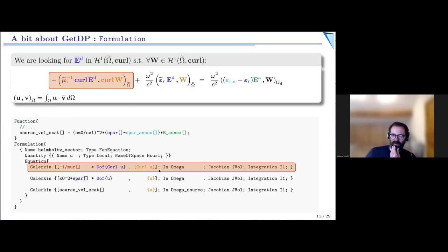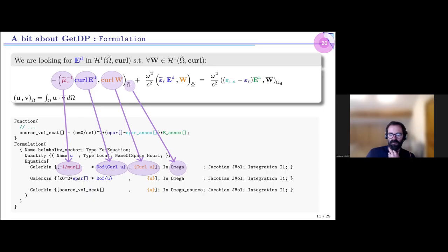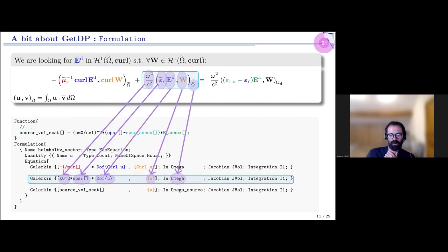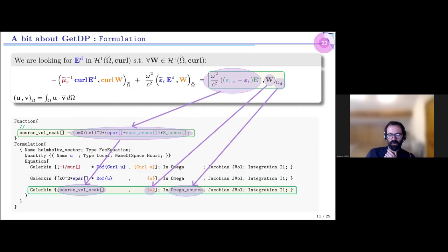So you see that this GetDP syntax is quite close to the original mathematical one. And moreover, if we examine each term, it becomes quite easy, even though sometimes they're not so obvious to write. It goes the same for all the terms in the equation. And so in the end, it's just a way to try to convince you that it's not so hard to actually write some variational formulation into GetDP, because it's the spirit of GetDP to be closer to the mathematical formulation, the mathematical discretization of a finite element problem, than to physics itself.